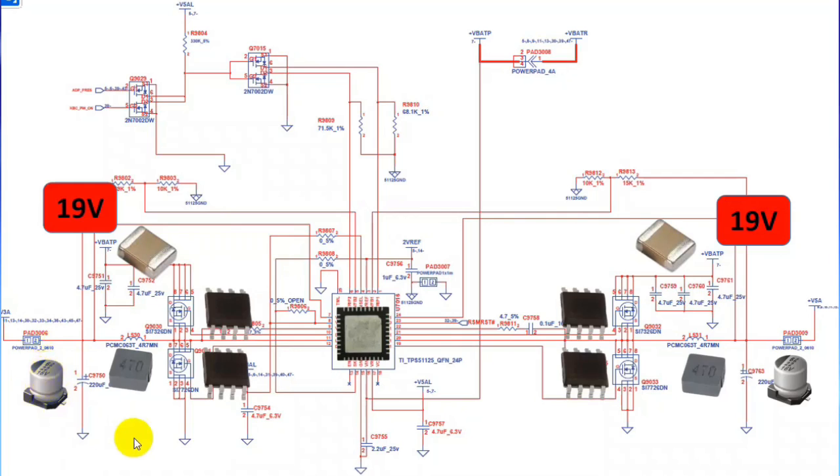So you can wonder, you can ask me, what is the purpose of this lower MOSFET that is connected to the ground? Basically this MOSFET has the purpose to adjust the voltage here. For example, we need to get here 3 volts or 3.3 volts. Let's assume that we get, for example, here 4 volt or 5 volt. So this MOSFET will adjust the current and eliminate the extra voltage to the ground, as you can see. Okay, so this is basically the working principle of the 3 volt 5 volt circuit.